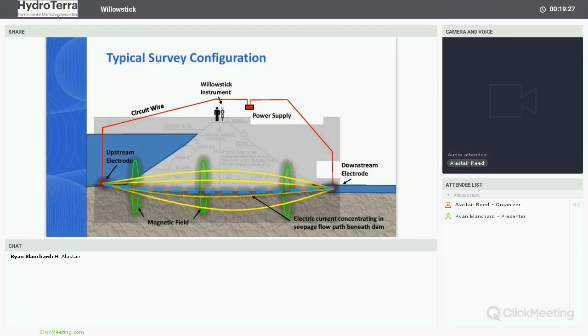So I guess by placing these electrodes in specific areas, we want to energize the study area from multiple perspectives. We've said we can use wells, seeps, reservoirs, and by doing this and energizing this area, we can have a high degree of confidence in picking up potential groundwater flow paths.